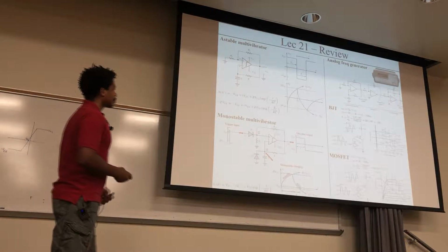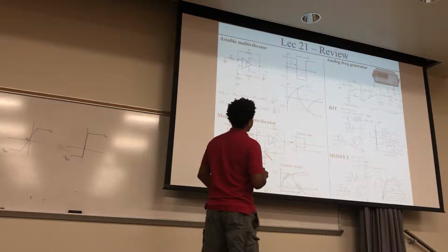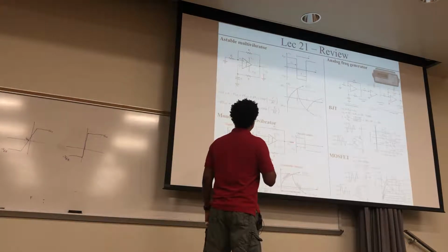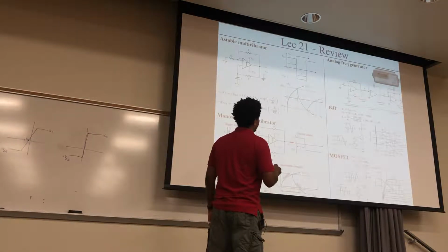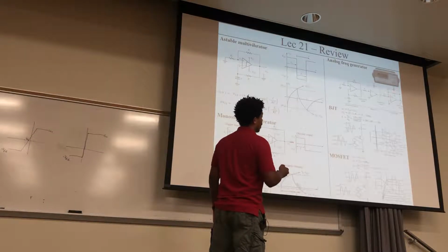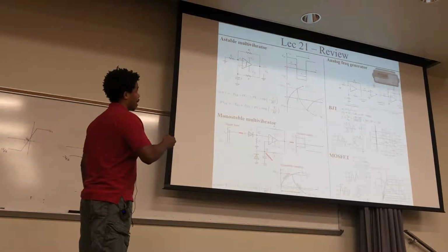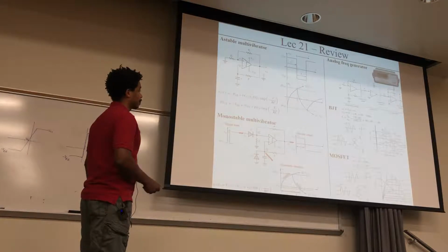Another thing we looked at was the analog frequency generator. Since we know how to oscillate using op amps, we have this astable multivibrator give us this rectangular wave right here. Then we can integrate that to get a ramp instead. Then we can filter that ramp through a low-pass filter, filter out the high frequencies, and turn the ramps into rounded curves that are sort of sinusoidal.